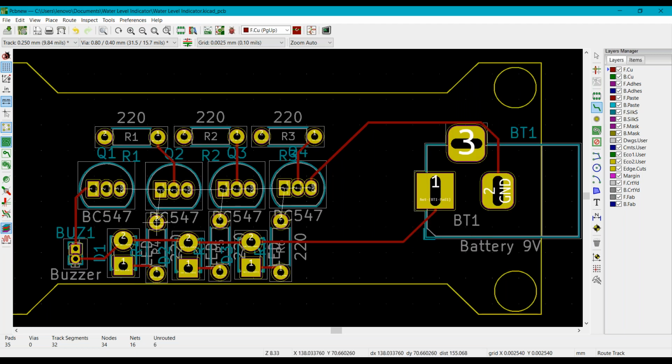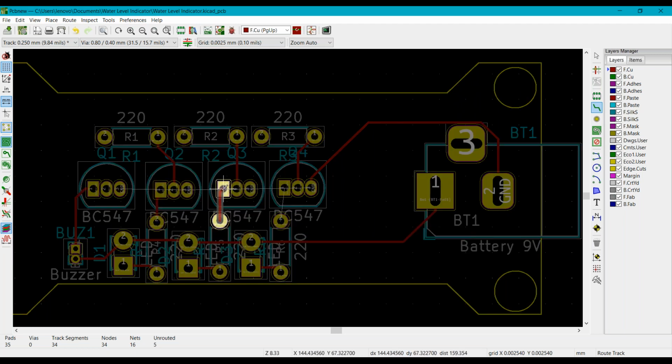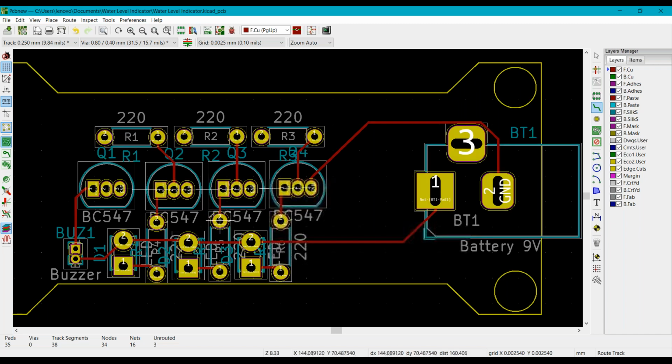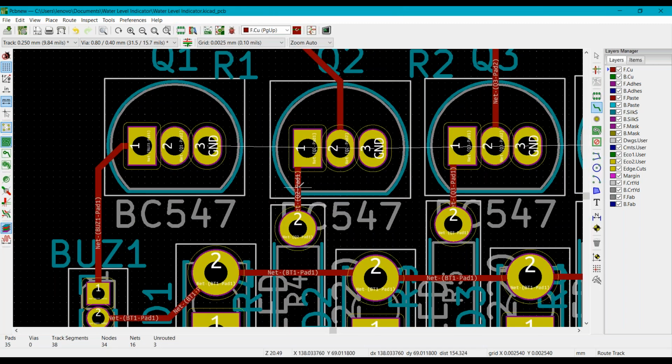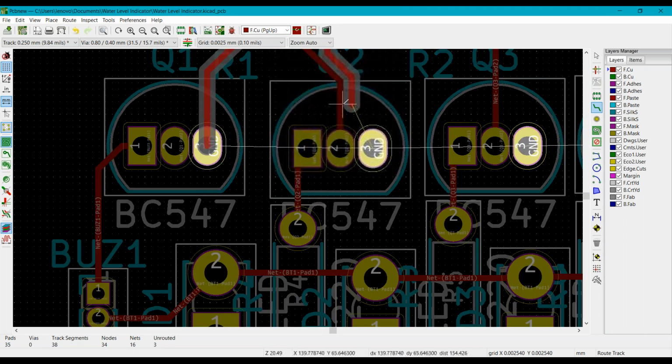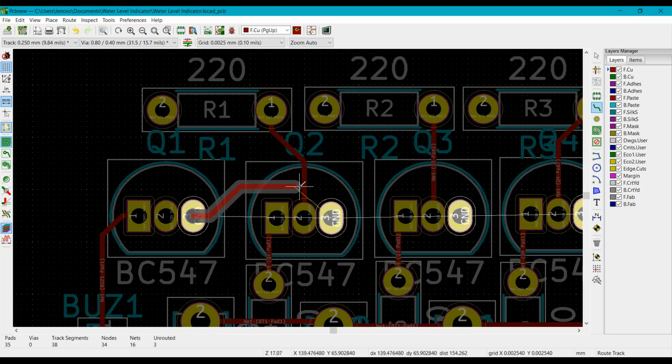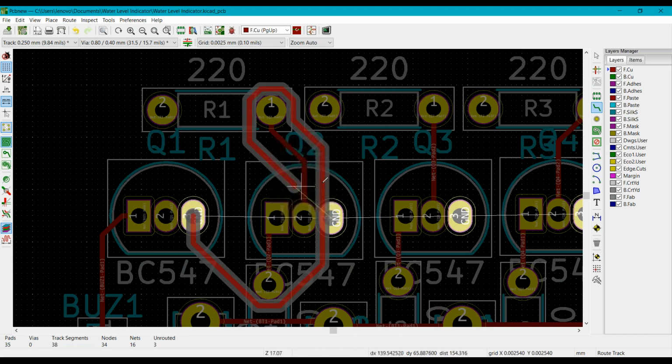Now you can see one thing. These are all the possible ways I can put the F.Cu tracks on the top layer. Now I won't be able to connect this because there is already a pair of wires on the top layer, and we can't cross this line.